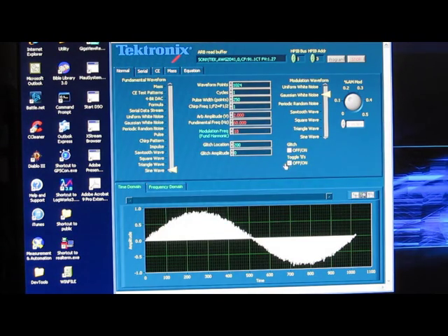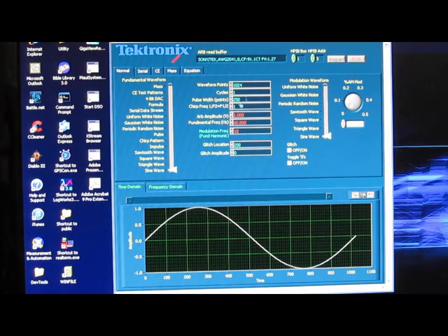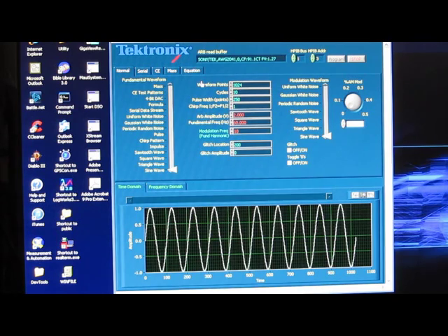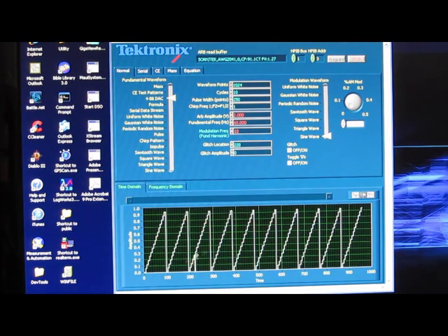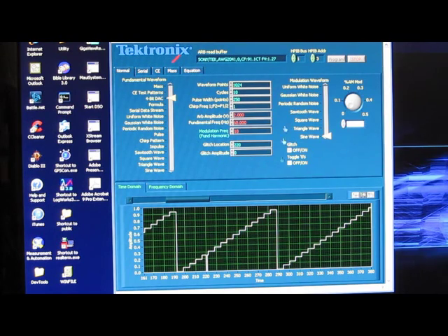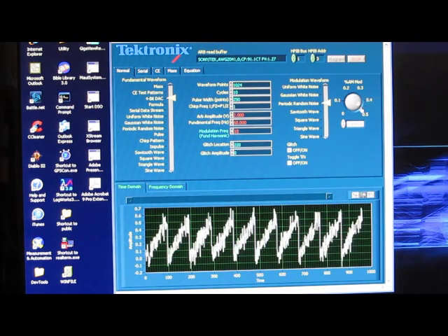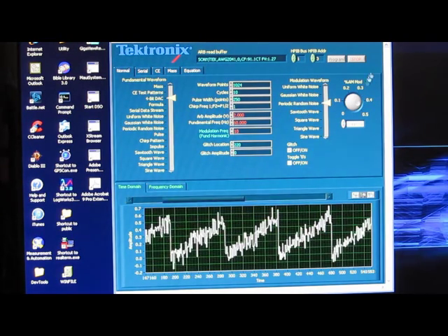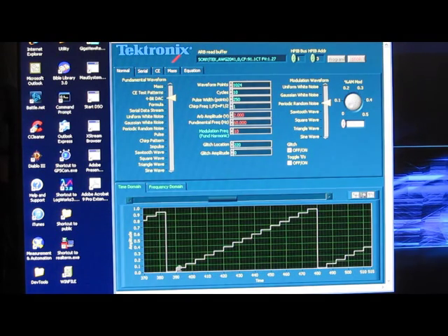I can also do toggle zeros where every other sample is set to 0. You can also program in the number of cycles you want. So I can do like 10 cycles, and then I can enable our glitch. So as we can see, 1 out of the 10 now would have a glitch in it. See the same thing for a DAC. Nice thing with this, for example with the DACs, if there were no noise, we'd expect to see 16 discrete levels representing the 4 bits.